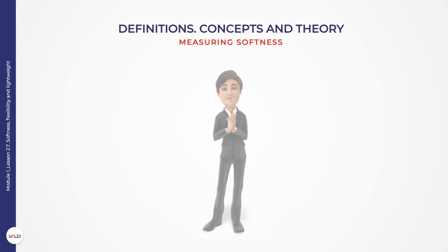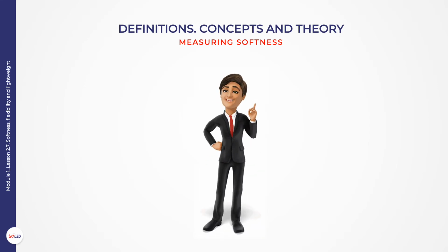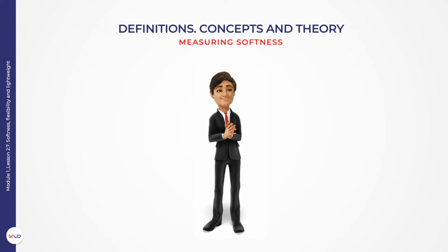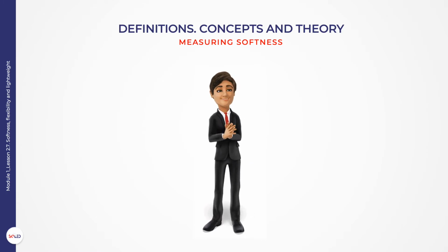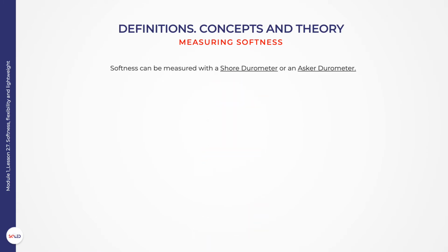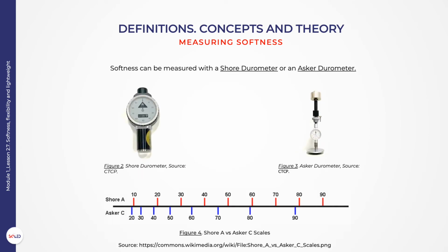To measure the softness/hardness of a material, it is necessary to use a durometer. Higher numbers indicate harder materials while lower numbers indicate softer materials. Durometer is typically used as a measure of hardness in polymers, elastomers, and rubbers, materials that are commonly used for manufacturing footwear bottom components like soles, midsoles and insoles. For testing shoe rubber and plastic, a Shore scale durometer should be used, while an ASKER scale durometer tester is used to test the hardness of any foam components for footwear.